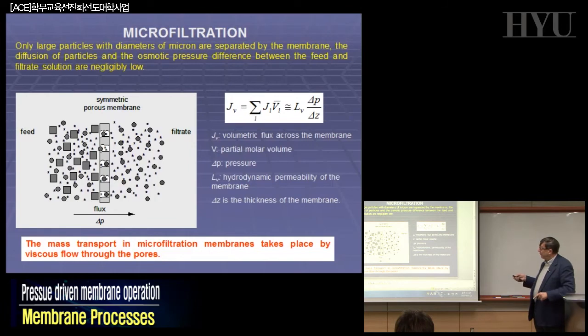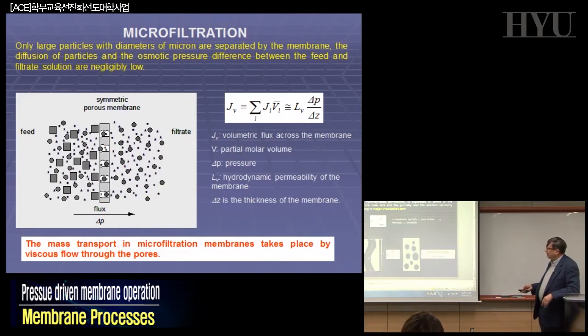And one of the ways of doing this is to operate on this one. So remember, when we discuss membrane distillation, or if you are doing research on membrane distillation, you have to optimize the thickness to minimize the heat transfer across it. Very different than microfiltration. Basically, the mechanism of transfer is nothing more than a viscous flow through the pore. So you can use the Hagen-Poiseuille equation, and this is the one that characterizes the system.